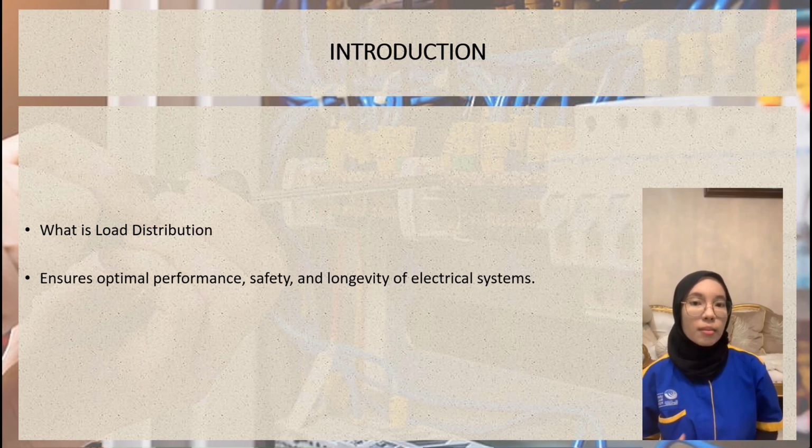Load distribution is the amount of power consumed by an electrical device or system connected to an electrical circuit or network. Load is an important factor in forming an electrical system. It is very important to ensure that it can supply power safely and efficiently to all connected devices. Why is load distribution very important? Because when designing an electrical installation, engineers need to calculate the amount of expected load to ensure that the electrical system, including wiring, circuit breakers and transformers, can safely handle the expected power demand without overloading and causing safety hazards such as overheating or fire.